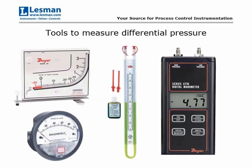So when approaching a burner like the Maxon Kinetizer LE burner, really there's a couple of different tools that you can use for measuring the differential pressure. I'm sure a lot of you that are familiar with tuning burners and have adjusted your own burners probably have some of these in your toolkit. This is just a number of Dwyer manometers that we have available. Really there's a couple main differences between these, and it's based on the range of operation.